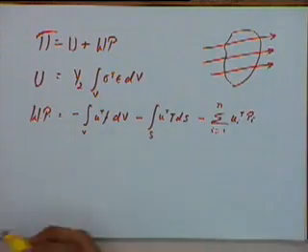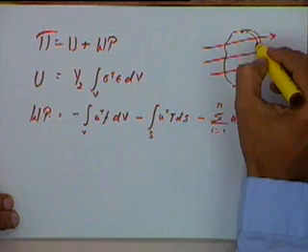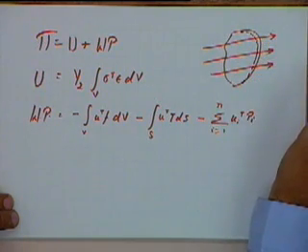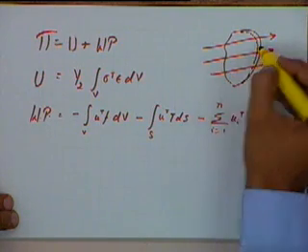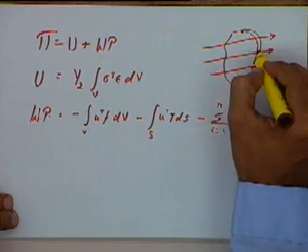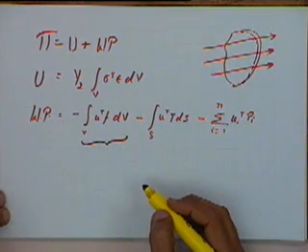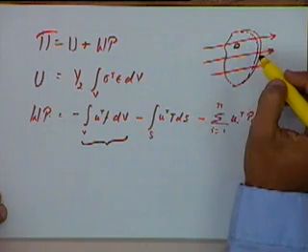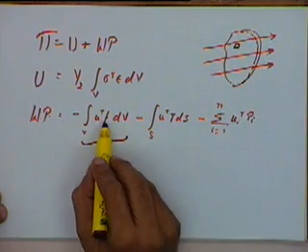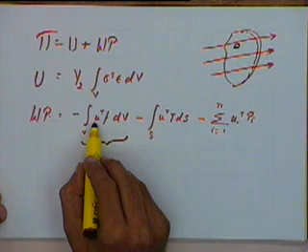If this object undergoes the deformation and it gets deformed like this, then in carrying out this deformation we have done work against this force, that is this component. So at each element inside this body the work done will be U transpose into F, work done per unit volume. U transpose is the displacement, F is the force.